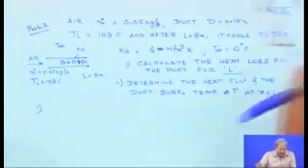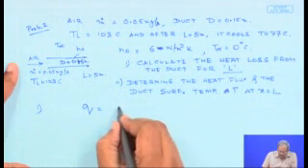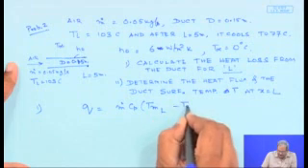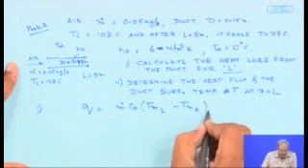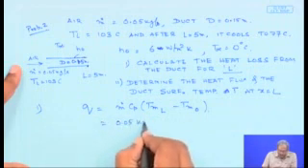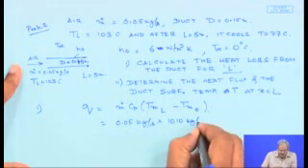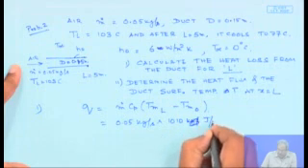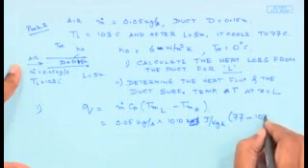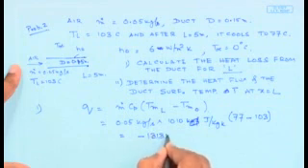When I calculate the first one, from energy balance I can simply find that the total Q is m dot Cp times Tm at L minus Tm at x equals 0. So, m dot is 0.05 kg per second. The value of Cp is provided as this much joule per kg Kelvin, and the temperature drop is 77. It was entering at 103, and therefore the total is going to be minus 1313 watt.